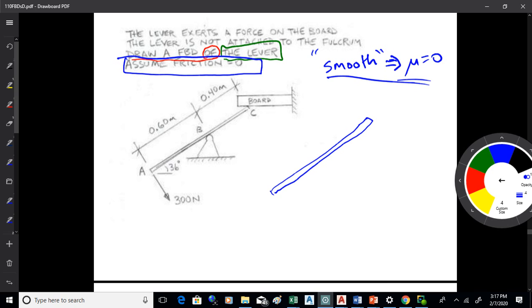And I think on this one, the thing to figure out is what is the flat surface, okay, as you're doing. If we were to do both surfaces, there could be 2 normal forces. Are there 2 spots where there could be a normal force? Yeah, B and C, I think.